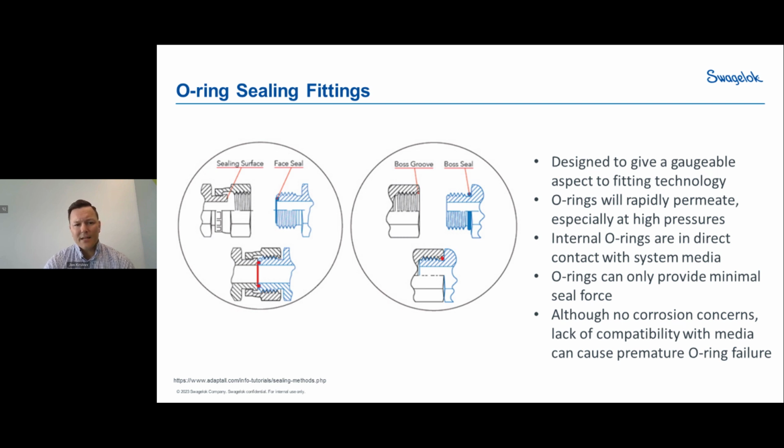And then finally, there is a bit of a corrosion concern with certain O-ring fitting designs, where if there is an entrapment area, you could have corrosion concerns depending on the interaction of the fluid and the material of that connection.